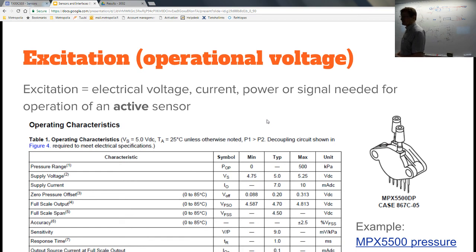There you usually have one transistor and so on, but that's something you can find in any good electronics book. If you have a PC, you have that audio jack. By default, it's designed so it gives that excitation voltage to a capacitive microphone.